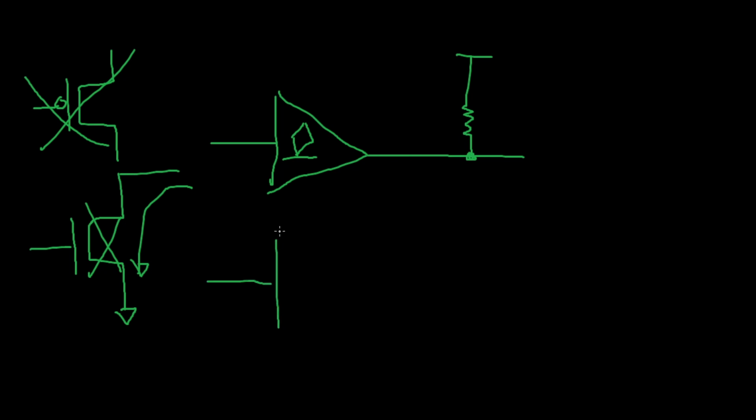If you put 2 of these in parallel, or really any number of these that you want in parallel, then what's going to happen is whenever they both pull low, they're just going to be making the line 0 volts. They'll be in parallel. If only one is low, then the line will still be low. It just won't have as low of a resistance pulling it to ground.